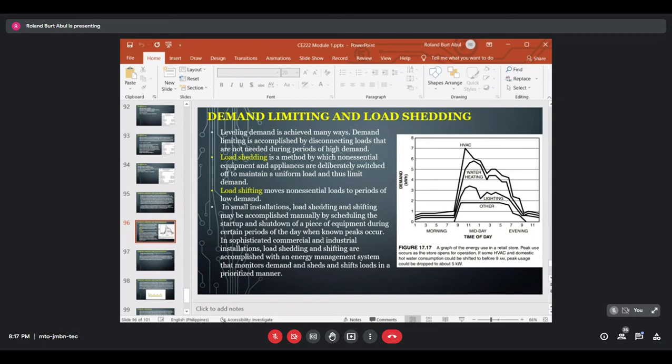Okay. So, as shown in the previous examples, a one-time peak in maximum demand caused the manufacturer an extra demand charge of $7,490.40 per month. When billing rate schedules for maximum demand is carried for 12 months, this equates to $89,884.80 annual increase.